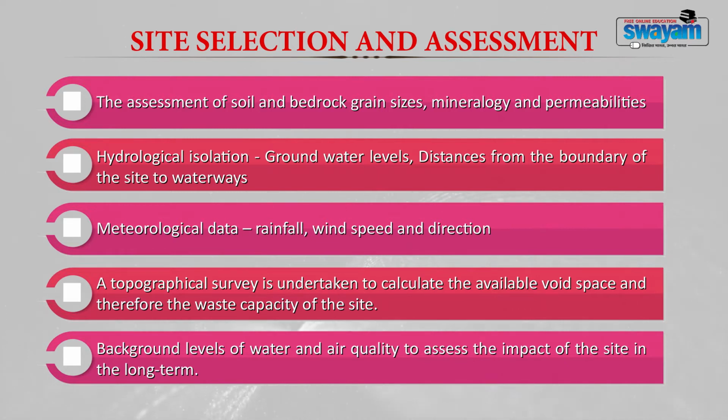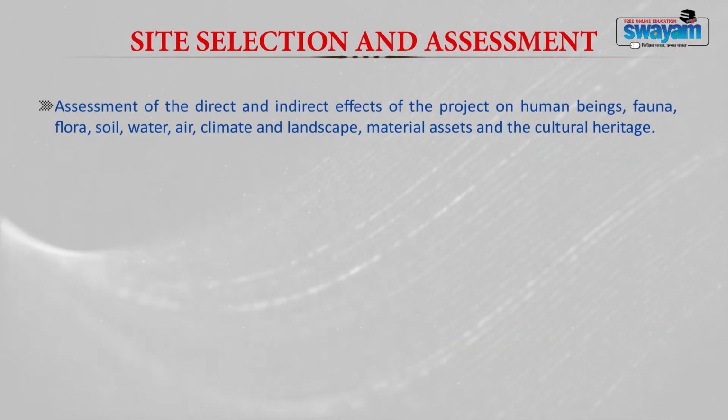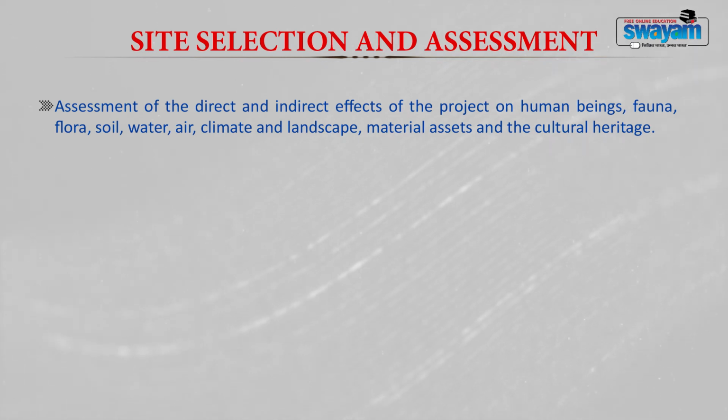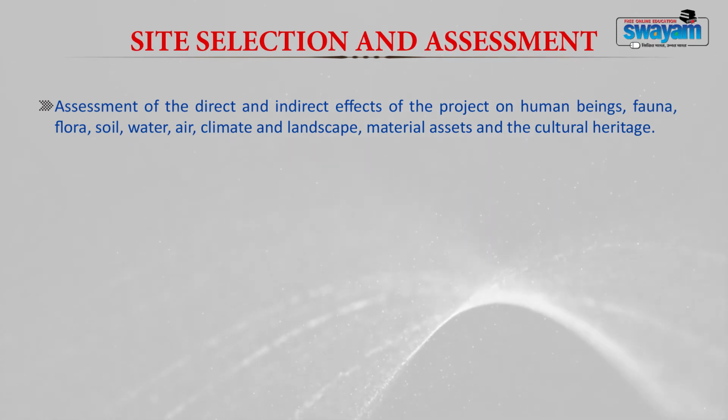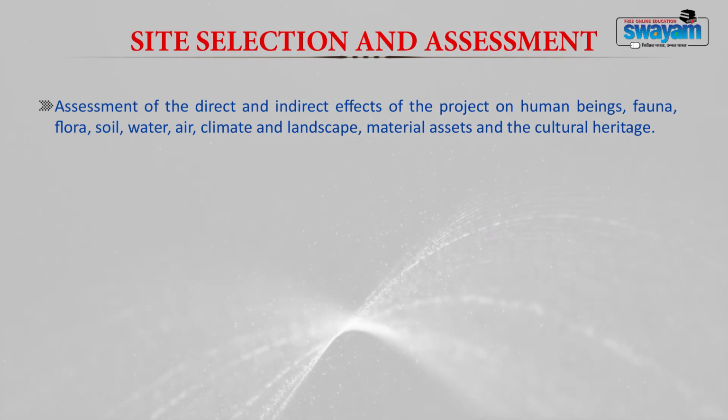During the process of degradation in the landfill, gases will be generated and these gases will be liberated into the atmosphere. So, if you have an air quality analysis before constructing the site, it will act like a reference, so that you can cross-check after, and you can use it for post-closure air monitoring. Also you should assess the direct and indirect impacts that it will create on human beings, flora, fauna, soil, water, air, climate and other landscape.